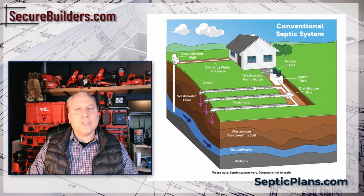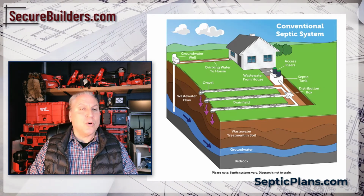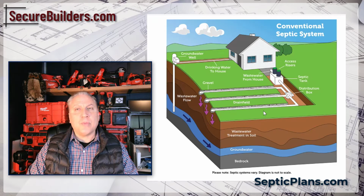The most important thing is your setbacks. The septic system has to be a certain distance from the house, and it goes by jurisdiction. Most times it's going to be at least 5 to 10 feet, sometimes farther. You're also going to have setbacks of your drain field from property lines. You're going to have setbacks of your drain field from escarpments, which is if there's a big hill or a cliff, it has to be set back from the escarpments. The drain lines themselves have to be a certain distance from each other, usually 5 or 10 feet.